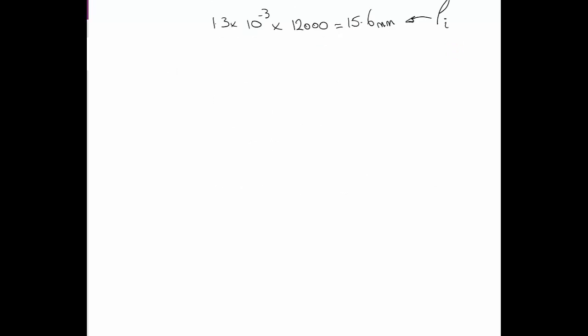Okay, all that preceding stuff was the undrained settlement. Worked on total stress, and it gives us that initial undrained settlement we've spoken about in the lectures. So now we're going to work on the drained case. The only difference here is we're going to use some drained parameters. Poisson ratio equals 0.25, and E prime, the modulus, equals 10 by 10 to the 3.